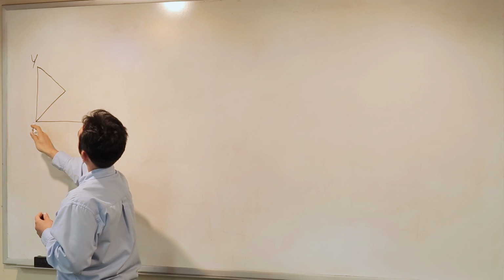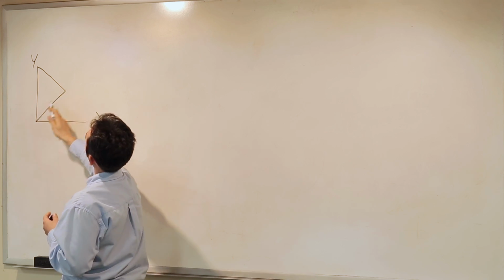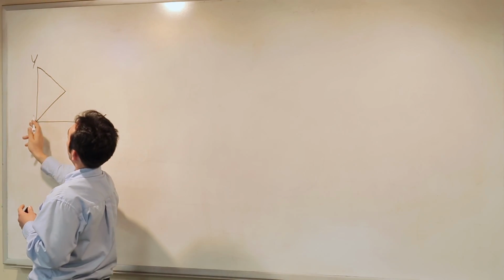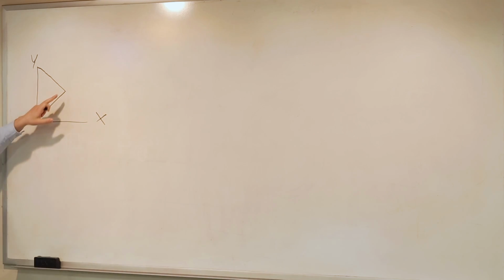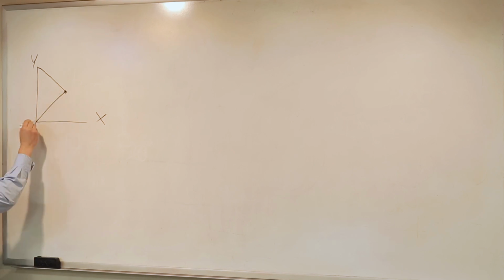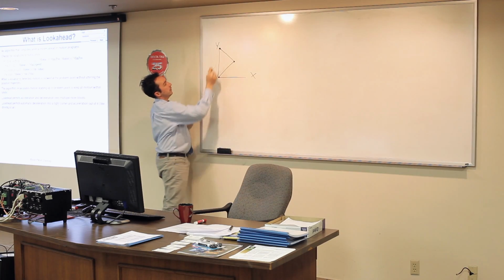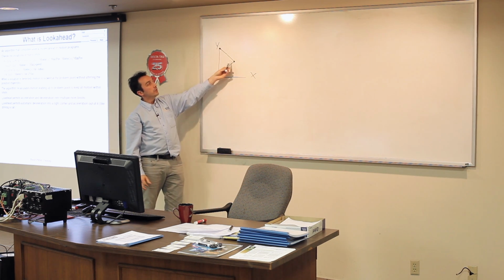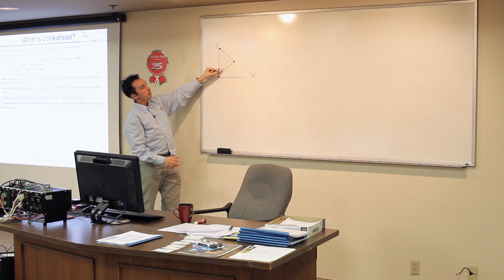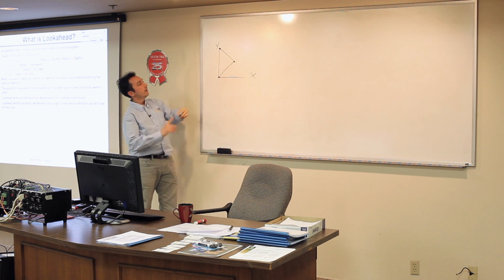The X will go, and when it goes here, the Y will be accelerating velocity, right? So at this point, it will violate Y velocity because it's going to keep going to that point. This is the starting point, this is the end point. So the Y will be accelerating, but it should slow down at this point to be able to make that corner.